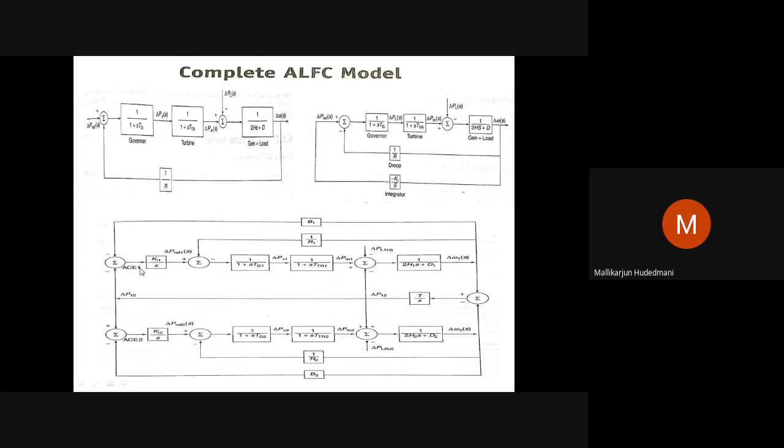Today we are trying to see what happens when you have interconnected operation with the frequency bias mode. Frequency bias mode means that as and when there is a fall in frequency, mechanical supplement as well as electrical power generation has to take place to see to it that the frequency drop is addressed by the respective area only. How does the controller in area 1 respond to a drop in frequency in its area due to its load?